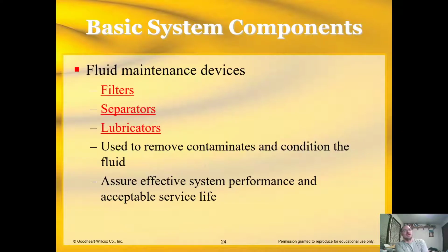Fluid maintenance devices. So maintaining a fluid, right? So you want to maintain the normalcy of a fluid. So either particulate, how much particulate's in there, or separators to keep fluid out of, say, your pneumatic systems. So water out of your pneumatic systems. Lubricators can spurt lubrication into, say, a machine or a device you're using. So say your cylinder doesn't start catching or seizing up after 100,000 repetitions, or if it's moving really fast, right? You need to keep things oiled.